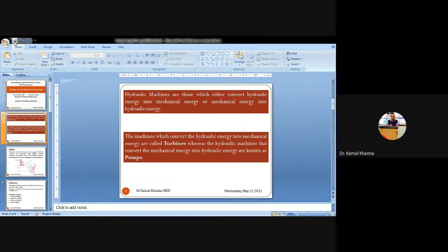Whereas the water pumps are receiving the mechanical energy, that is, as soon as you switch on the electrical power from the electrical source, they start rotating or reciprocating, which produces the mechanical energy. Then they start converting the mechanical energy into hydraulic energy, because by using the water pumps you are generating the hydraulic energy so that you can transport the water from one point to another point, whether you are increasing the pressure of the water or the potential energy. How are you increasing the potential energy? If you are transporting the water from the lower level to the higher level, you are increasing the potential energy, or you are transporting the water from one level to another with an increase in the pressure energy. So basically, you are converting the mechanical energy into the hydraulic energy with the help of the water pumps.